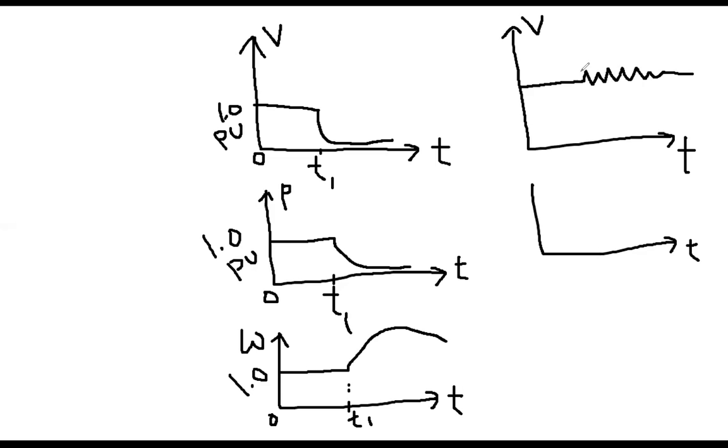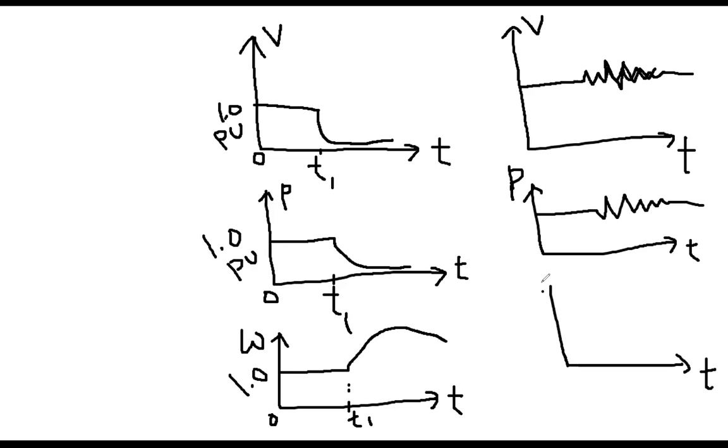Now it depends on the input torque variation. If you see, for example, little torque variation and then again here is big variation, then accordingly there will be fluctuation, because voltage will follow the input torque pattern. The same thing will happen for the power curve. We are assuming that initially it was fine, but then it is oscillating, following the pattern of the torque. The same thing will happen to your speed, because that torque is imposed on that speed mainly. Initially it was fine, but then it will also oscillate. This means that all three parameters will oscillate.